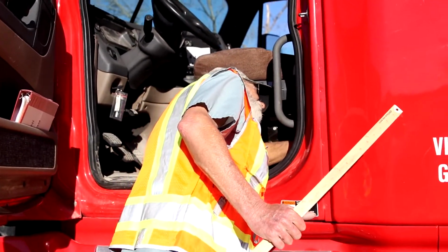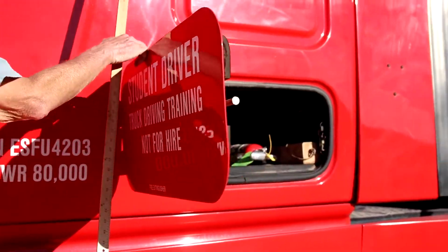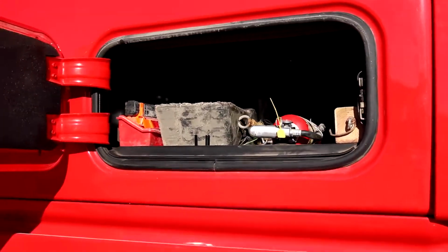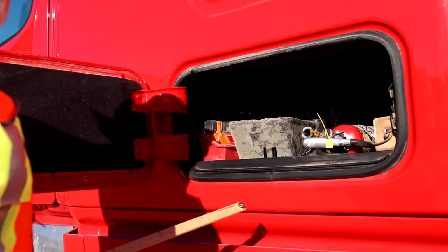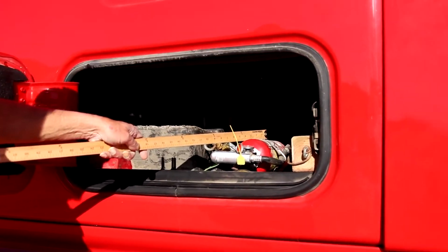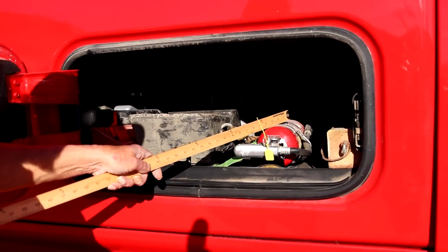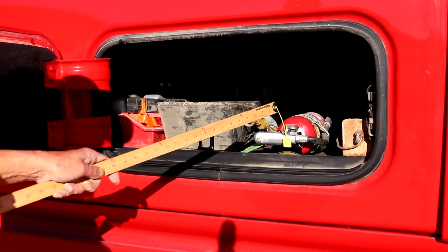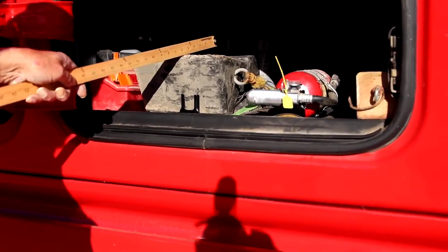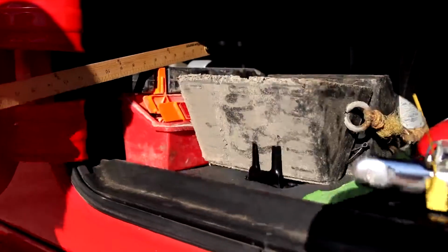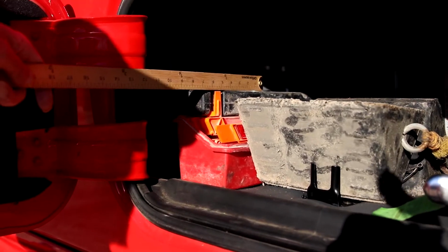Then, there it is. Open that. Inside your cargo box, you have an ABC type fire extinguisher. Should be securely mounted, fully charged, up to date with a tag, with a safety pin in it. Next, we have a set of wheel chocks, just in case you need them, and a minimum of 3 red and amber emergency triangles. They're not missing, damaged, or broken either.